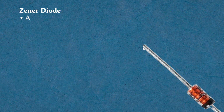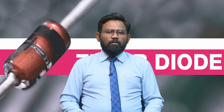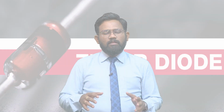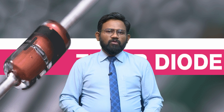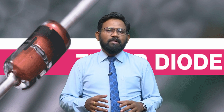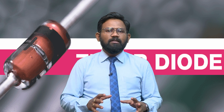Now what is Zener diode? A heavily doped PN junction diode that works in reverse bias condition is called a Zener diode. Now here the word to be noted is heavily doped. Normal PN junction diode is having some impurities. We have studied in the past lectures that PN junction diode is formed by inducing the impurities in the semiconductor materials. So the level of doping can be changed, it can be increased or decreased. So to form a Zener diode, or to make it different from a normal PN junction diode, the doping is increased, and the diode which is heavily doped is called the Zener diode.